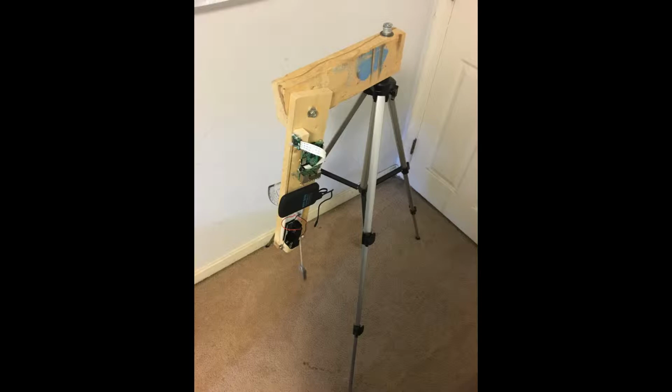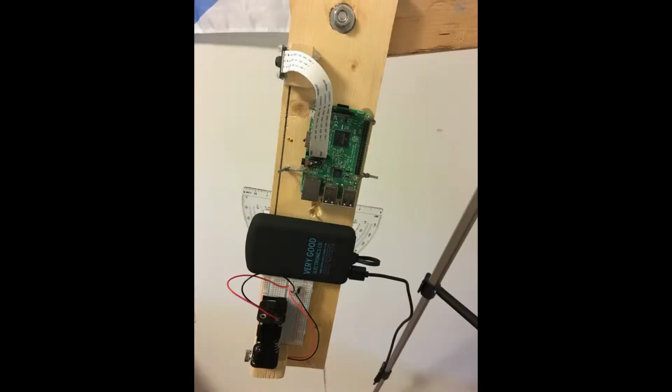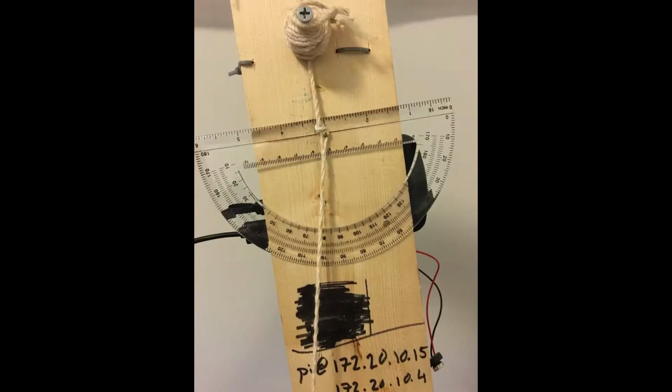Computer vision was used to locate and isolate the line laser in each image using an HSV mask for that line. A geometrical relationship between the distance from the camera to the laser transmitter and then to the target is used to create a mapping from pixel location in an image to distance in the field.